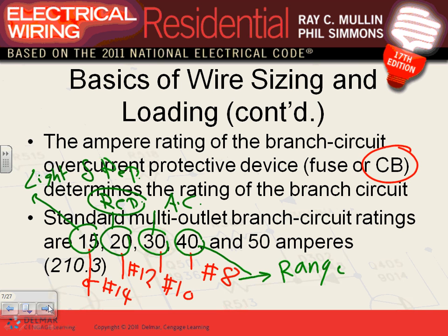Any question, guys? So when I say I have a circuit that feeds the air conditioning, what is the rating of this circuit? You're going to say this circuit is a 30 amp circuit. The rating of the circuit goes by the rating of the overcurrent protection device. Let me tell you an example why this makes a difference. Why can't I call this circuit a number 14 circuit or a number 12 circuit? No, because the conductor can change. The overcurrent protection device is the most important thing in the circuit.